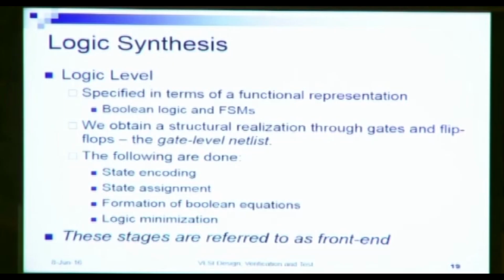So what do we do here? We do the following: state encoding, state assignment, formation of Boolean equations, and logic minimization. So at the end of the front end of the logic synthesis step, we have a minimized digital circuit corresponding to the functionality that we had at the beginning of our architectural synthesis step.